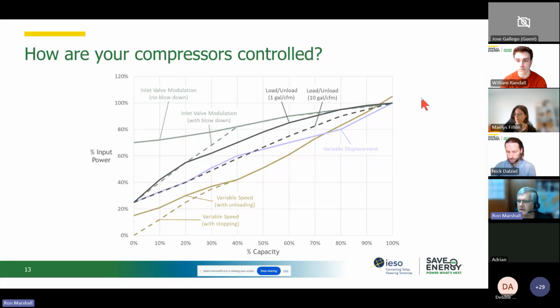And you didn't need that air, what happens is the system fills up with air and the pressure starts rising until something pops, right? So there's a need to control the compressor. So if you had a 1,000 CFM compressor and only 500 CFM of load, you somehow have to get that compressor, it may be the only one you have, right, to put out 500 CFM, right?